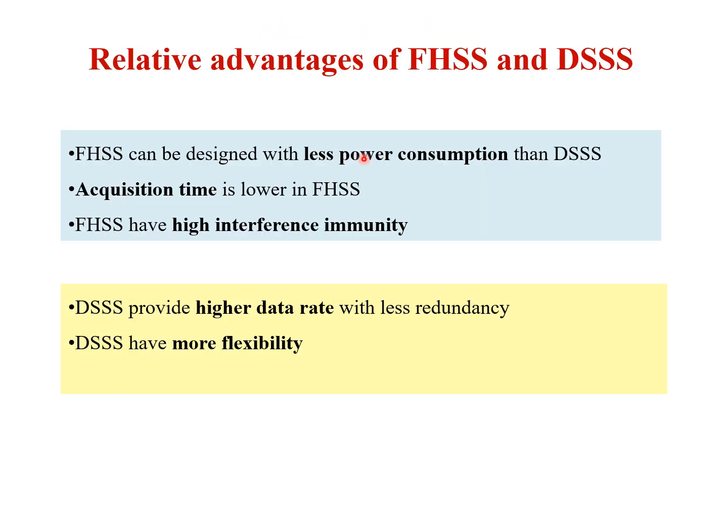The relative advantages of FHS and DSS. FHS can be designed with less power consumption than DSS. Acquisition time is lower in FHS. FHS has high interference immunity, and DSS provides a higher data rate with less redundancy, and it has more flexibility.